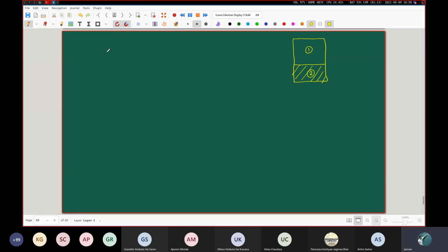It's true that we have this expression sigma 1 is equal to minus E1 y by rho. The moment I write this, you see the value of whatever we have been writing till now. So even though we are developing an alternate method, it is based on the basic theory, or the extension of the basic theory, which we have been talking about till now. So we have these two expressions.